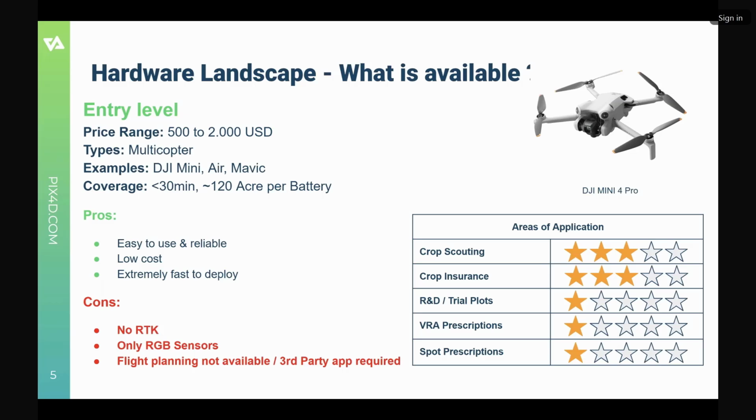However, if you're going to fly a large area, what would be a good aircraft to choose possibly? Like a Wingtra or a Quantum or something like that, or a SenseFly, right? You're going to fly a lot more acres with a lot less battery. You're going to have an hour flight time, or an hour and a half flight time. But that's more of a Texas-sized drone, right? That's going to get something covered and get something done. The smaller quadcopters are about 160 acres per flight, roughly. So they're also going to give you a fairly decent resolution, almost all of them. Although some of those bigger systems are going to give you a much higher resolution depending on the camera that they have.